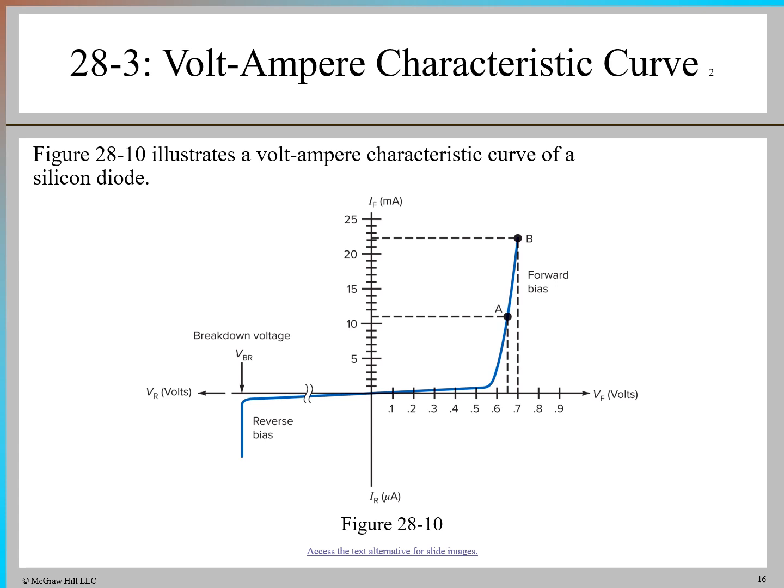Diodes should never be operated in the breakdown region as it can lead to damage. However, as long as the reverse current and voltage stay within the diode's power rating, the diode will recover. Rectifier diodes typically have breakdown voltages greater than 50 volts.